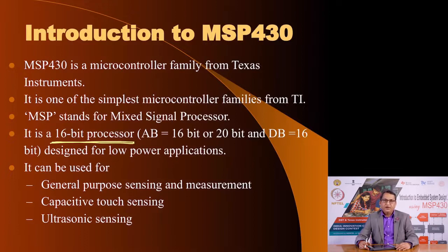The memory and peripherals and various types of memories can be accessed using an address bus, which for most cases is a 16-bit address bus, which means it has 2 raised to power 16 memory locations. And in some cases when you want more memory than is possible with the 2 raised to power 16 combinations, it also uses a 20-bit address bus. The data bus is 16 bits.